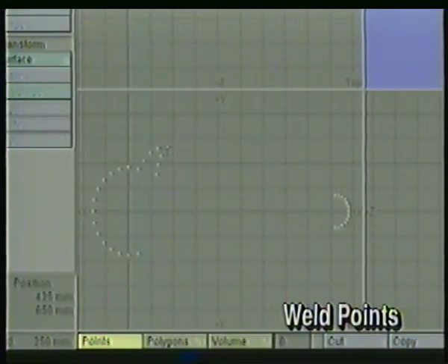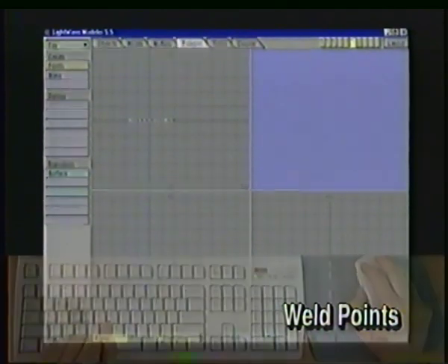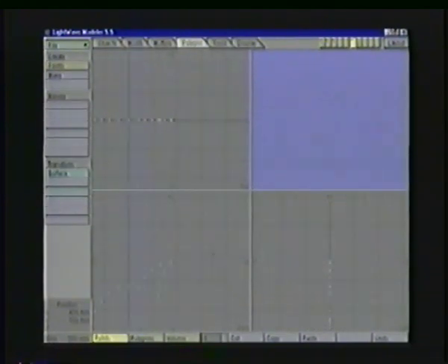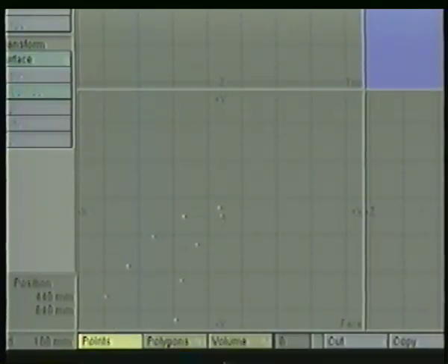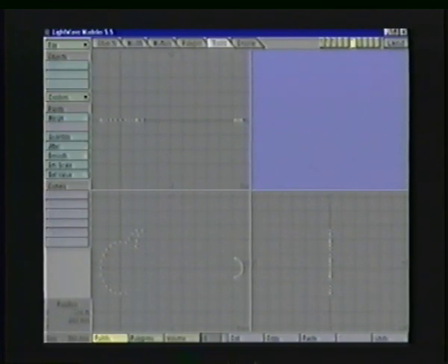and zoom in by placing my cursor over the points, hitting G on the keyboard to center under my cursor, and then hit the period key to zoom in. I'm then going to select the 2 points and weld them together. Weld is under the Tools panel. I could have just deselected one, but I wanted to make sure that I brought them to the same location. So now we have a little spike sticking out of our leg.